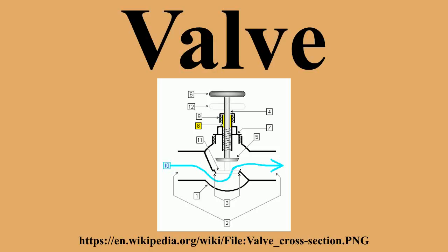Control. Many valves are controlled manually with the handle attached to the stem. If the handle is turned 90 degrees between operating positions, the valve is called a quarter-turn valve. Butterfly, ball valves, and plug valves are often quarter-turn valves. If the handle is circular with the stem as the axis of rotation in the center of the circle, then the handle is called a handwheel.